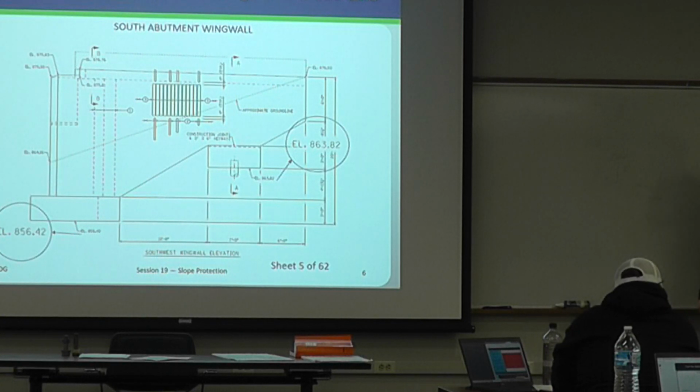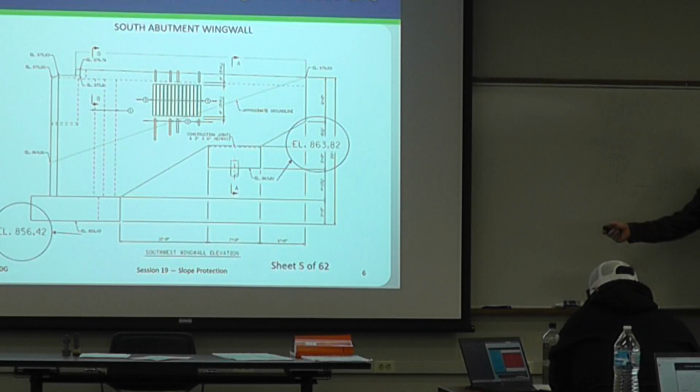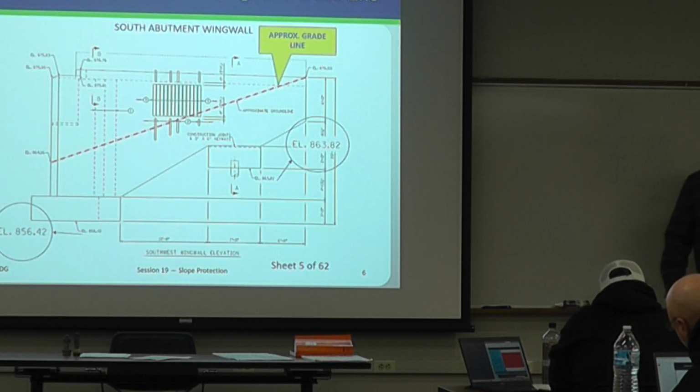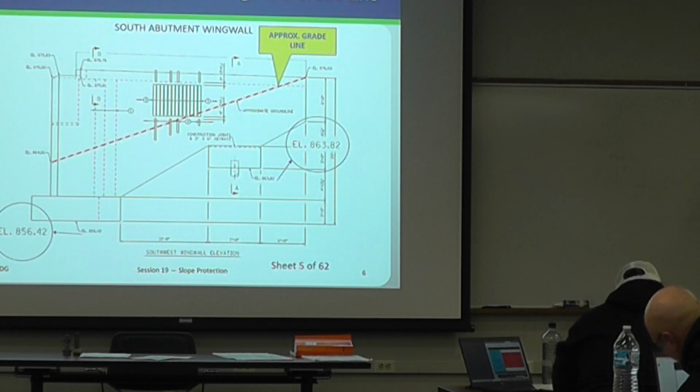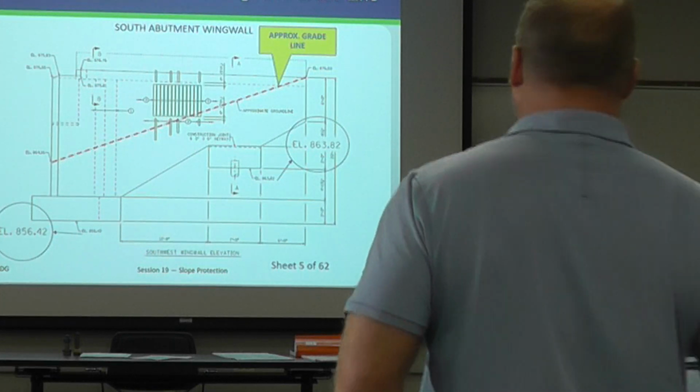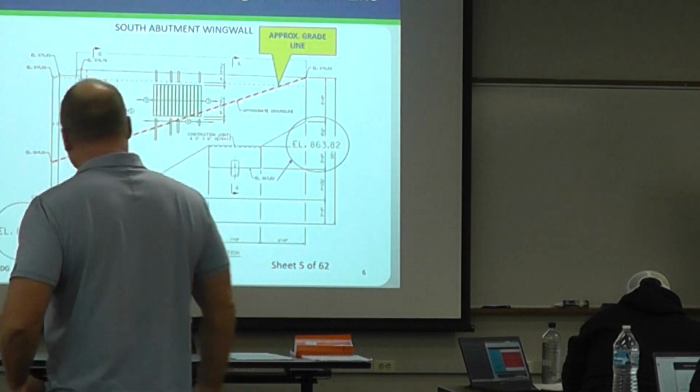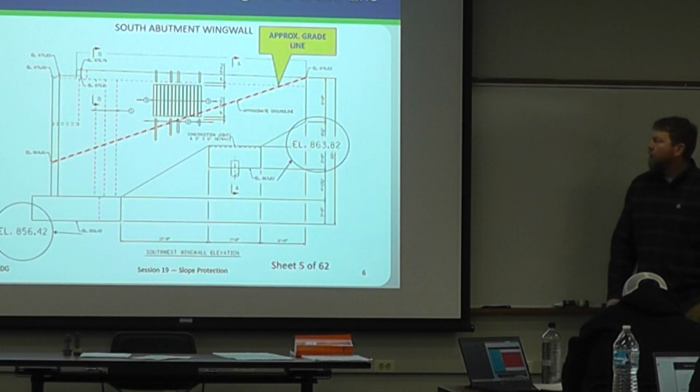So usually they'll have a leader arrow with the elevation pointed to both, and that's what the contractor is going to use to establish elevation. They'll also use that to establish where the pile cut off. Not that we're going to cover that in this section, but how about the ground line? There are 2 elevations that assign where that ground line meets the front and the back, or the upper part. What are those 2?